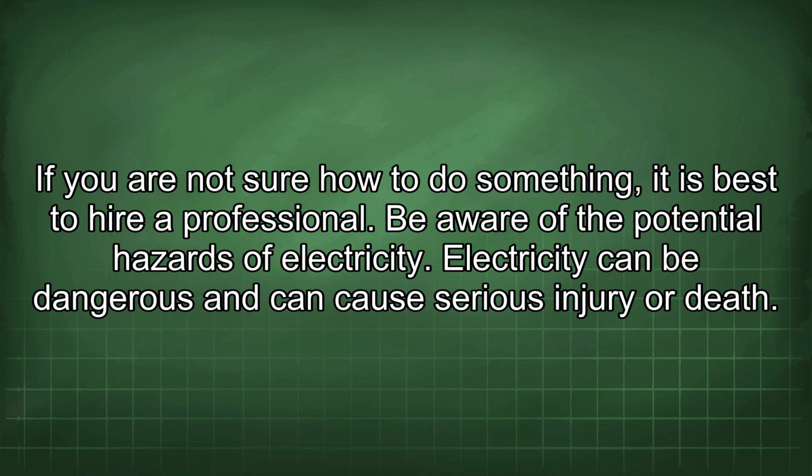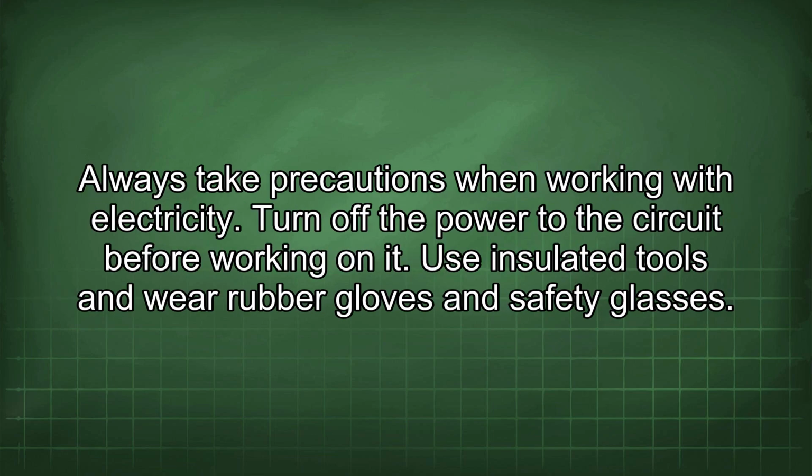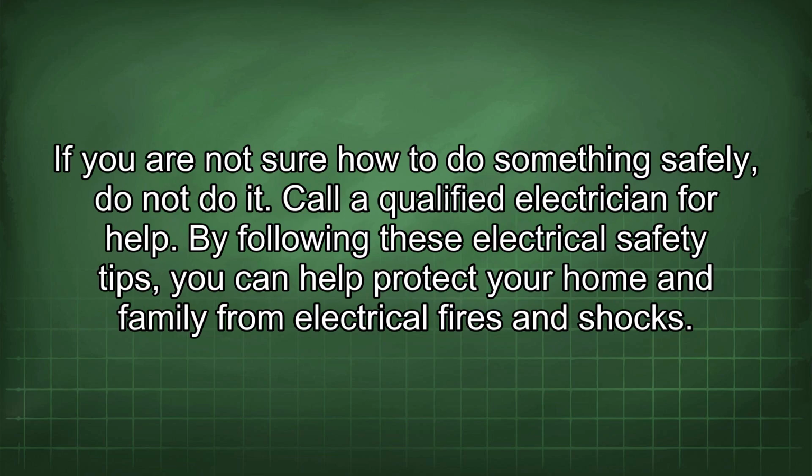Be aware of the potential hazards of electricity. Electricity can be dangerous and can cause serious injury or death. Always take precautions when working with electricity. Turn off the power to the circuit before working on it. Use insulated tools and wear rubber gloves and safety glasses. If you are not sure how to do something safely, do not do it. Call a qualified electrician for help.